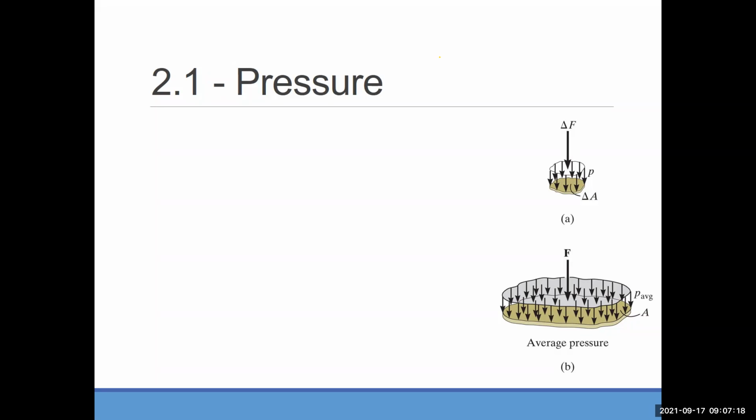We discussed pressure and shear stress both. So pressure was what actually? That is exactly the same definition for shear stress. So there is one specific point you need to make sure: the force is perpendicular. Yes, you need to mention that the force is perpendicular to the cross-sectional area. And sometimes we name that normal stress, right? And if it's parallel, we will call that shear stress.